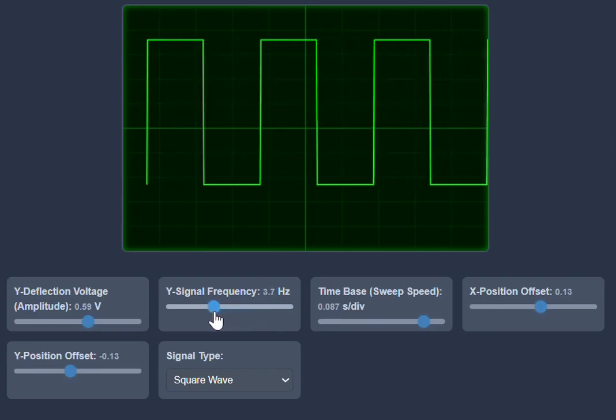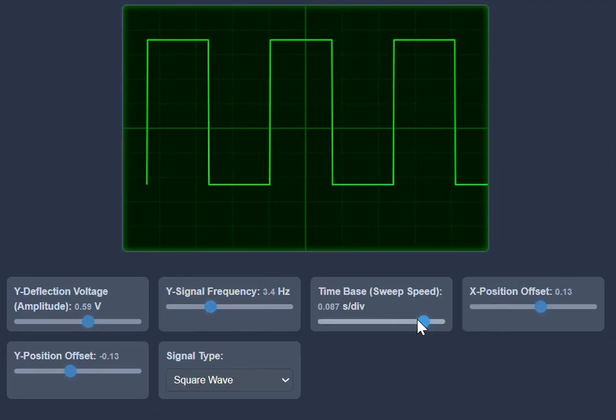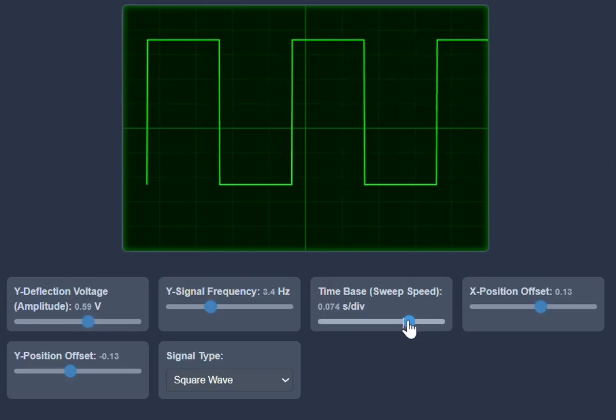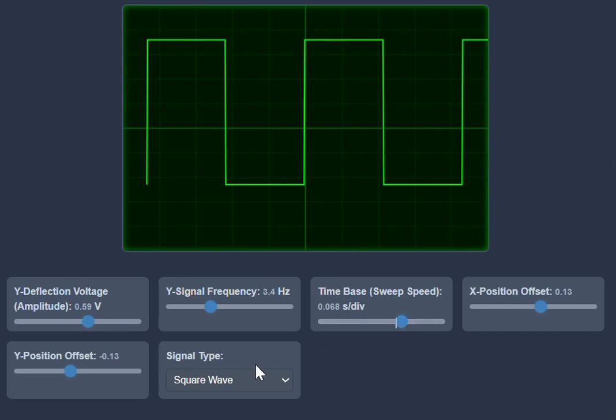So what do we do? The y-axis changes, and if you need to change the signal's time speed, how do we do that? Now you can easily measure the amplitude on the y-axis and the time period on the x-axis. That means you can also measure the frequency, how much frequency there is in a single cycle, and the amplitude of the signal using the CRO.